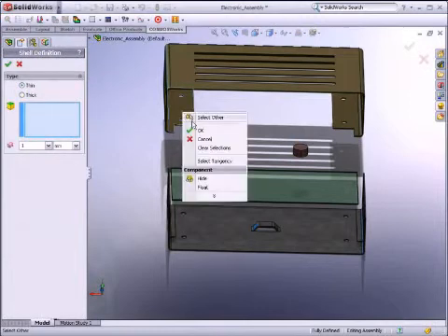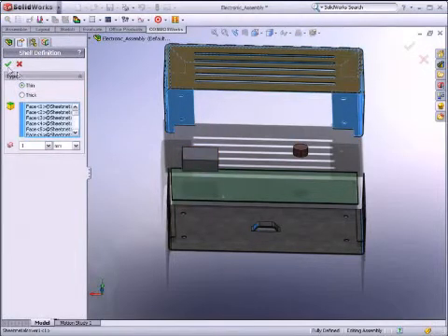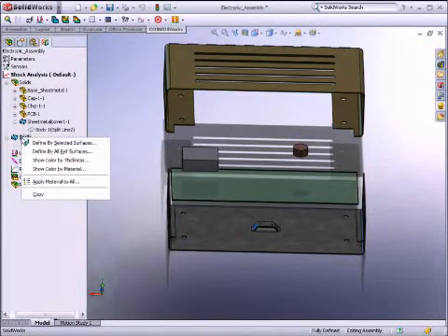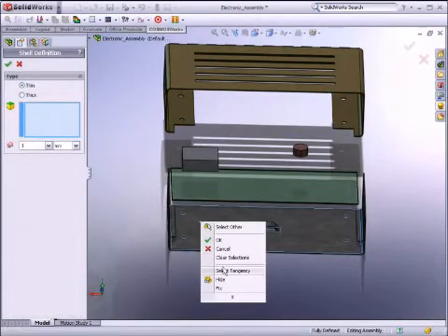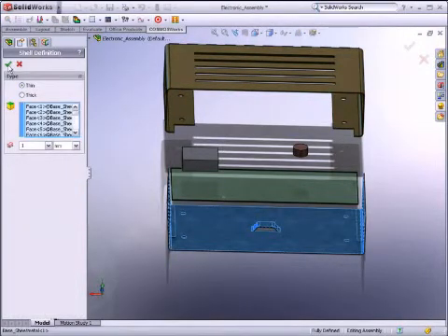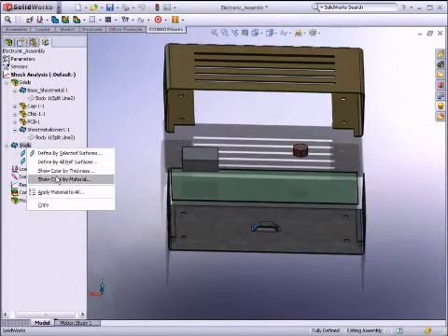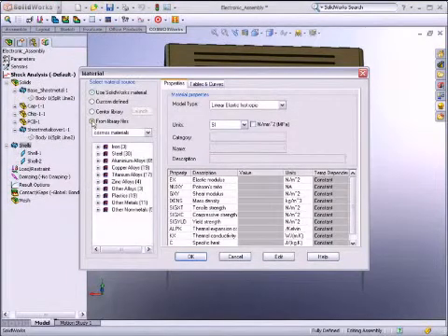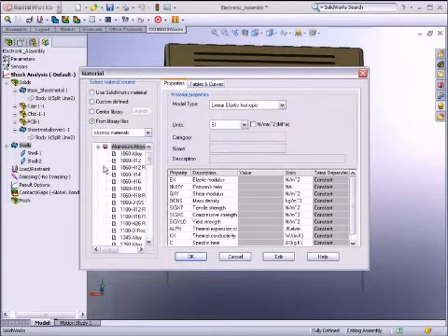For this sheet metal part, we can use shells to simplify the meshing and solving process. With sheet metal, the outside surfaces are normally all tangent, so you can select all faces with just a few clicks of the mouse. You can apply separate materials to the shells or use the default SolidWorks material if it's already selected.